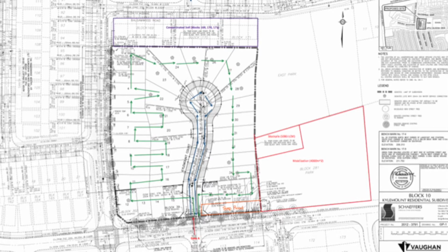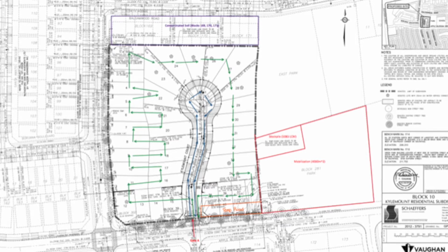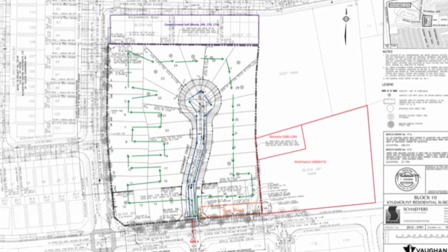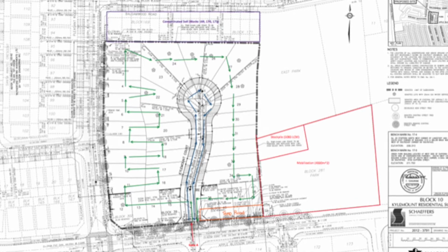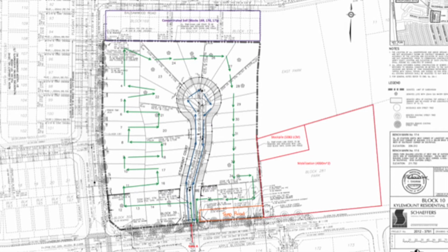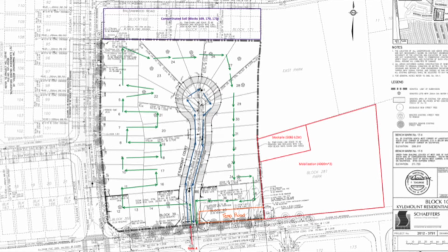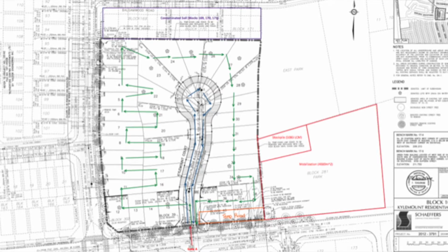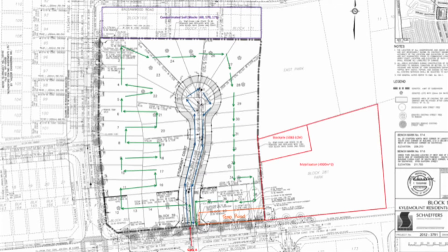The green arrows on the drawing represent the sequence in which the lots will be graded. This route limits the distance traveled by equipment, therefore lowering costs and ensuring no repetition. The lots closest to the mobilization will be completed last to minimize the disturbances to the final grade caused by frequent equipment movement in this area. The blue areas on the site layout show the path traveled by concrete and asphalt crews to maximize efficiency by using the cul-de-sac as a means to safely turn machinery and trucks around while exiting the worksite.